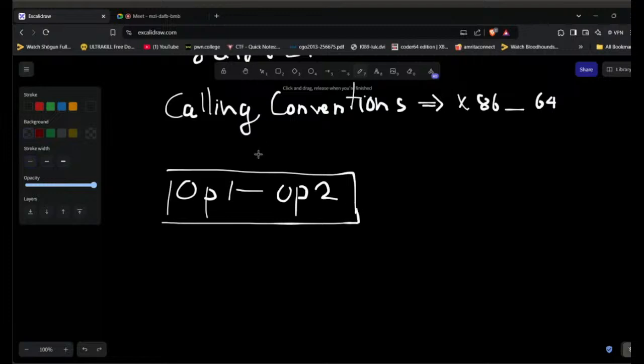Okay, if you guys remember, we probably discussed something called the flags register. The flags register contains a lot of stuff like the sign flag, the zero flag, and currently the zero flag is what we need to care about. The zero flag is a 1 bit that is set when any particular operation gives the result zero. Now, when I compare two numbers, if they are equal, if I am comparing 5 with 5, what happens when we subtract both of them?